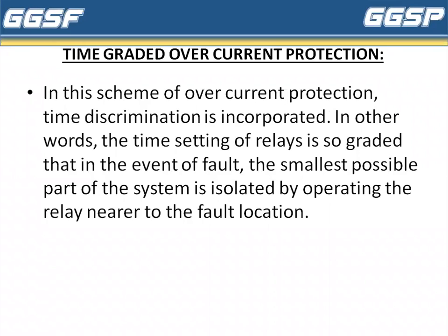Time graded overcurrent protection. In the scheme of overcurrent protection, time discrimination is incorporated. In other words, the time setting of relays is so graded that in the event of fault, the smallest possible part of the system is isolated by operating the relay nearer to the fault location.